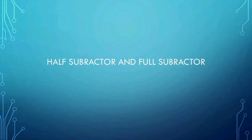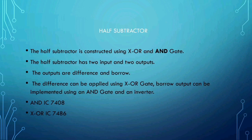Half subtractor and full subtractor. Half subtractor. The half subtractor is constructed using XOR and AND gate. The half subtractor has two inputs and two outputs. The outputs are difference and borrow. The difference can be implemented using XOR gate. Borrow output can be implemented using an AND gate and an inverter. AND IC7408, XOR IC7486.